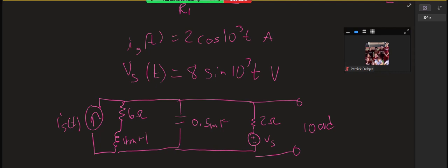And I know that I'll have optimum performance when the impedance of the input circuit is purely real. So I want to add something right here to make the input purely real.